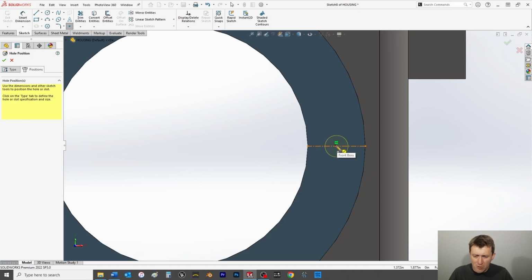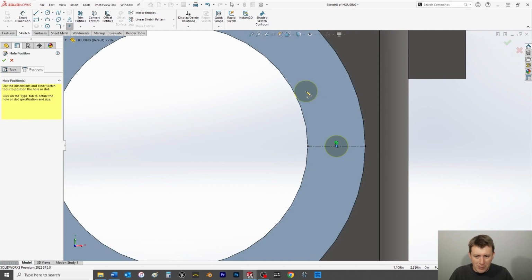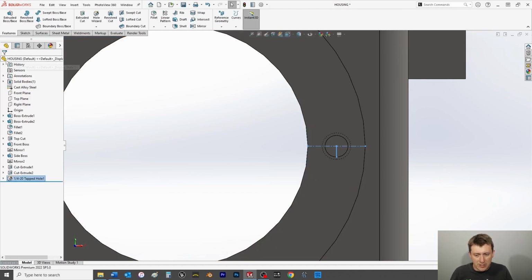And now I'm going to hover over my center line, construction line, synonymous there, and I want to choose the midpoint and make sure I'm coincident with that. I will then click, and then I will drag out, and that's going to take us now to page 82. Now, had you not, say you clicked up here somewhere, the top of page 82 will show you how to snap the relations for that. However, since I already did that, we're good to go. And I'm actually going to choose over here on the left and click OK.